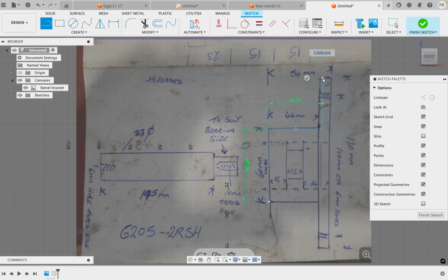And then out in this direction here, it is 54 millimeters, so that would be a 10 millimeter plate at the top. So the drawing's not 100% accurate, but we'll work with the dimensions, and we also want to come out from that midline, so we can kind of drag that out just to get us the midpoint there where we see the dotted lines, ensuring that it's coming down 90 degrees.